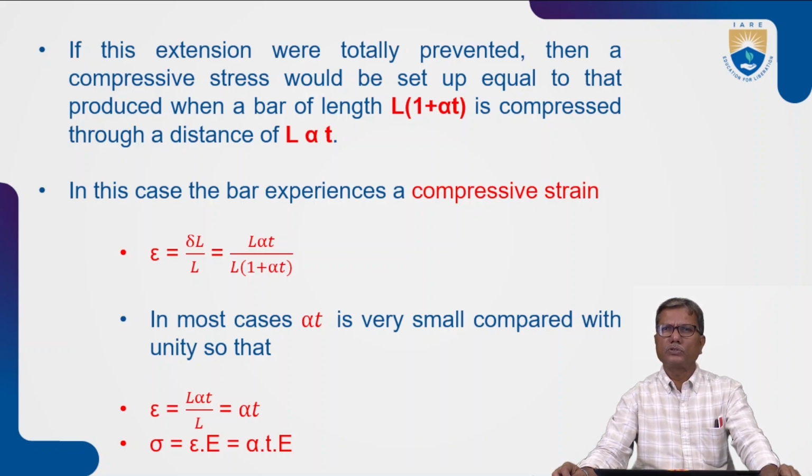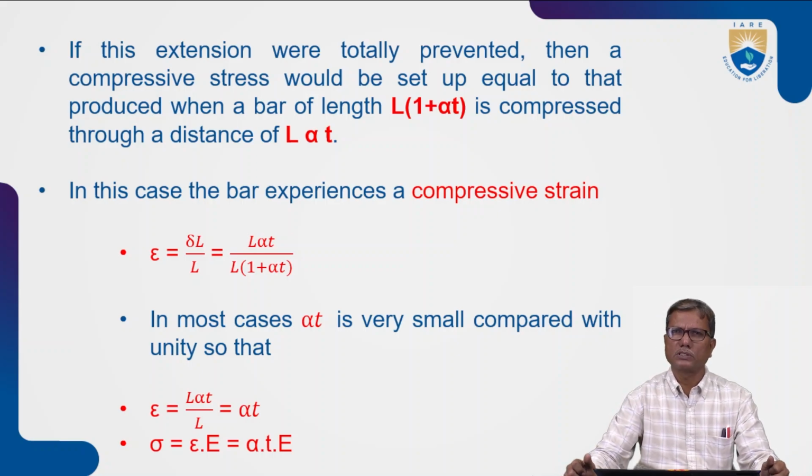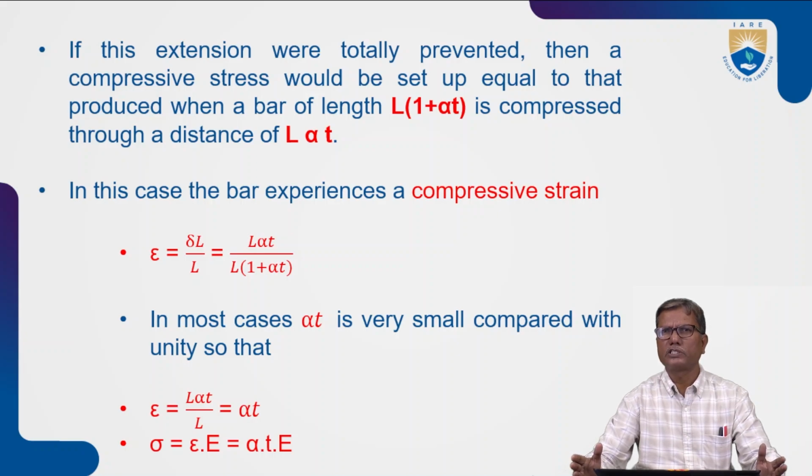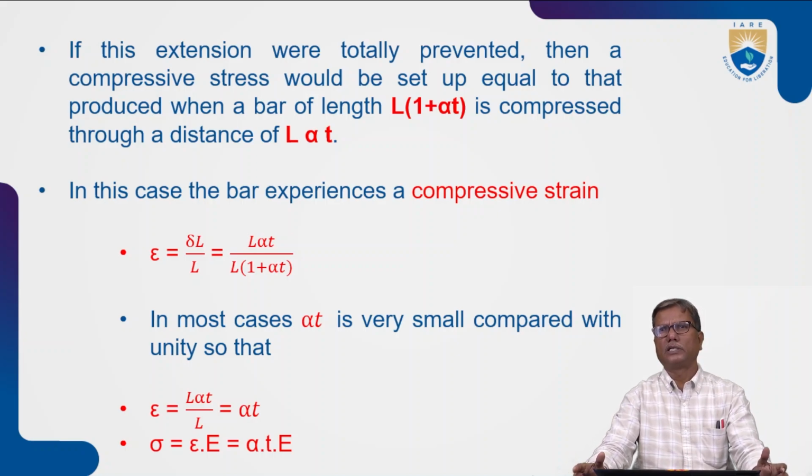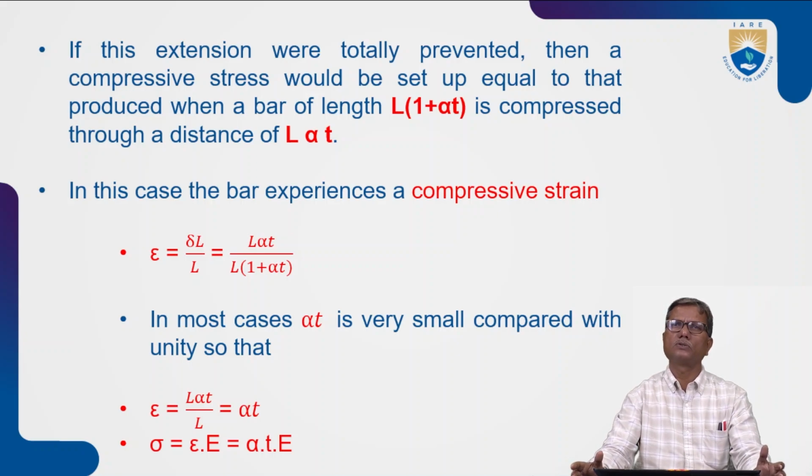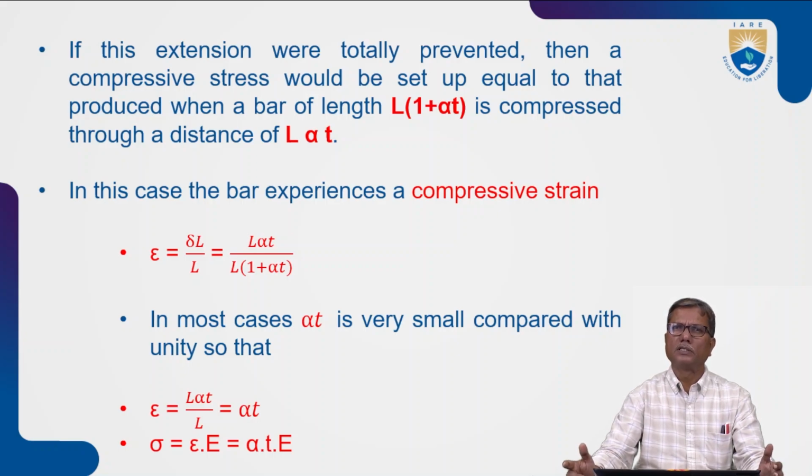Okay, so if it is restrained from free expansion or contraction, then the stresses will be developed because the supports are subjected to stresses. The supports which are restraining the expansion or contraction will be subjected to stresses due to change in temperature. For example, let us consider the rise in temperature. Then the bar will tend to expand.